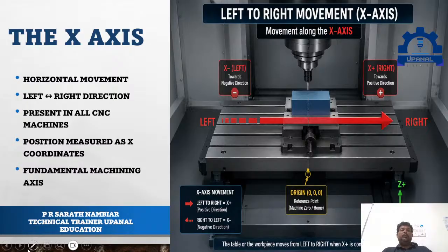When the machine moves along the x-axis, the x coordinate value changes. So in this move, only the x value changes. The other values stay the same or remain unchanged. This is because CNCs move by changing coordinate values along the specific axis. So the x-axis is always left to right movement. The left to right movement is known as the x-axis.